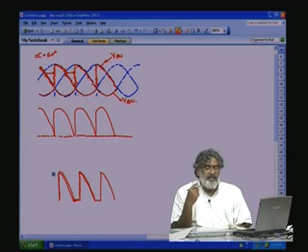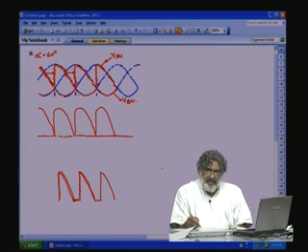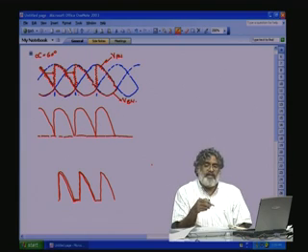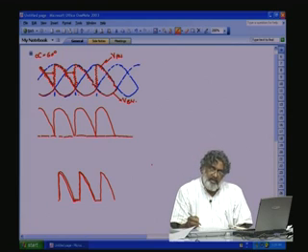That is the purpose. Now, so far we have assumed that the conductions are instantaneous, and there is no delay between the incoming thyristor and the commutating thyristor. The moment reverse bias is applied, we assume that the conducting thyristor will immediately switch off, but that is not the practical case.